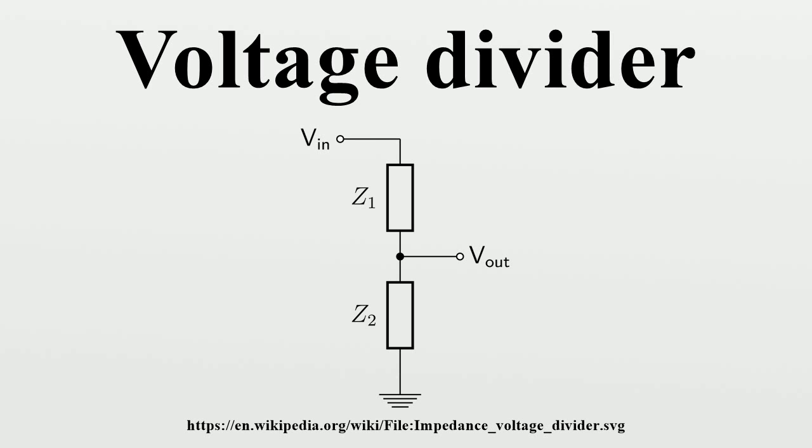High voltage measurement. A voltage divider can be used to scale down a very high voltage so that it can be measured by a voltmeter. The high voltage is applied across the divider, and the divider output, which has a lower voltage that is within the meter's input range, is measured by the meter. High voltage resistor divider probes designed specifically for this purpose can be used to measure voltages up to 100 kV.